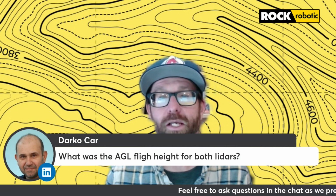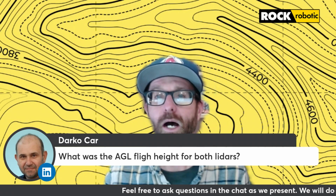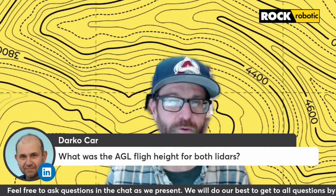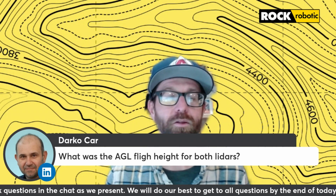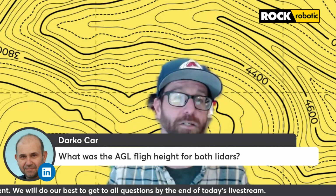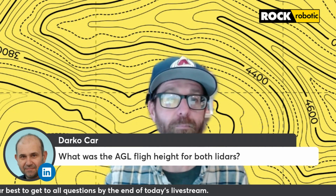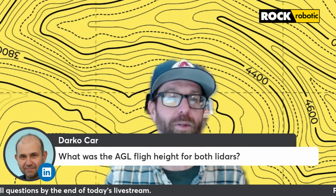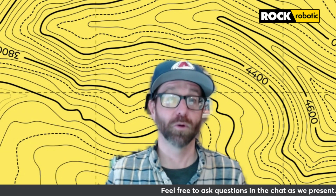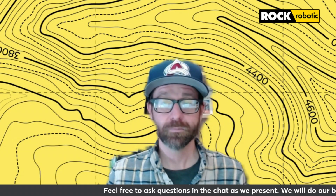Darko asked: what's the AGL flight height for both the LiDAR units? Those are going to be in the 45 to 50 meter range for the comparison ones with the R3 V2 and the DJI L2. For the two data sets where we didn't have comparison, East 56 Ave and Van Bibber, that was going to be 40 to 45 meters AGL.